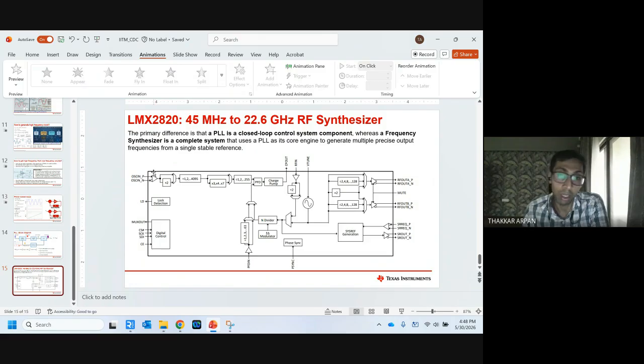So now what your question was, that instead of a crystal oscillator, you can make a low frequency circuit at the input itself, right? But that low frequency circuit, whatever you are going to make, let's say you build it with capacitance and inductance available commercially, a discrete LC circuit, same structure, same amplifier, same oscillator you are making off chip. If you go and see the data sheet of the capacitor manufacturer, it will say its capacitance is going to vary 2%, let's say, right? So let's say inductance doesn't vary, then your frequency at input can vary by 1%.